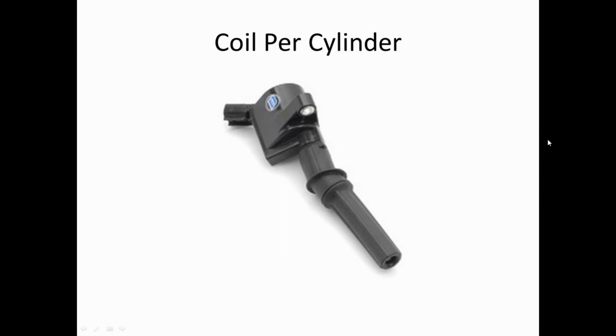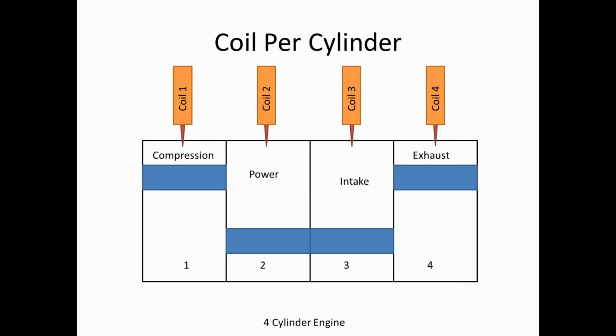I just picked the stock image off of Google, but I'd know that coil anywhere. These things tend to go out pretty often. They're not the best setup. They're kind of cheaply built. So regardless of whether you're replacing the spark plug wire or not, sometimes you just got to replace these coils. They tend to just commit suicide, and you get a random misfire happening on one cylinder.